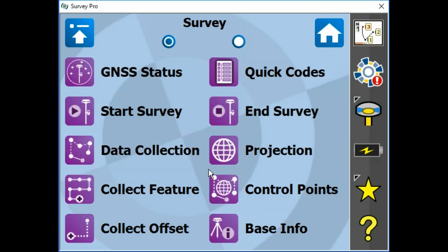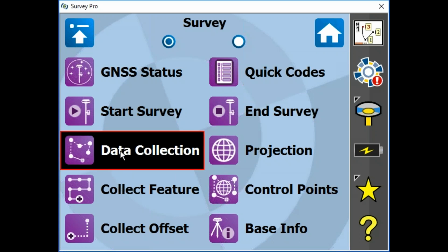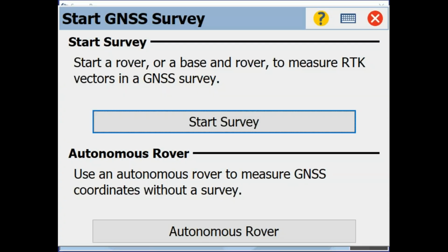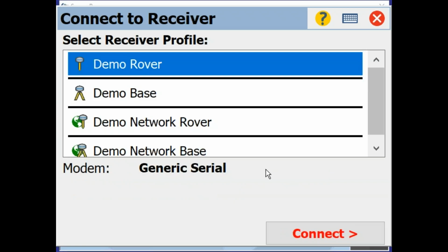We're going to do the example here where I'm working on mapping plane. So maybe if this was an NTRIP network, or maybe if I could set my base right up on one of my known monuments in that coordinate system, I could proceed directly to data collection like Joe said. If I've got a mapping plane, so now scale and orientation is known, all I need to do is set my point of beginning, and anytime I put my base on a known point of beginning, I'm ready to go. In this example, we're going to show you where you're obliged to calibrate, or the example of I've got to set my base on top of that hill because it is a secure location.